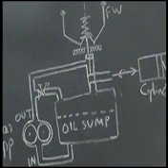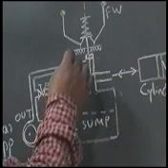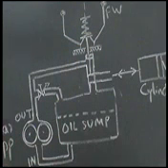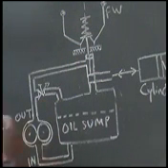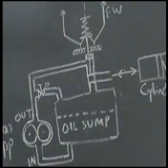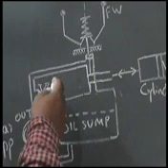That is why we use the conical spring. So at every point the same amount of force is required to bring a change in small elongation, which is very much essential to design the governor.